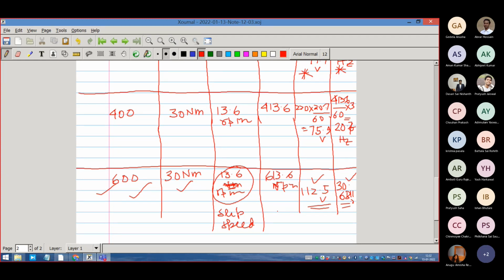Let us take the proportional part out. First think about an integrator, because the error is then integrated, it is trying, and the moment it is trying, it is going in the direction of reversing the error. Okay, it should be such that its intention is to reduce the error, right? So this way it will go increase, decrease, and finally it will settle. That's what you see as the oscillations in this. That is what the controller is trying by trial and error. It is trying, and ultimately it is arriving at the correct amount of slip that would be required in the system.